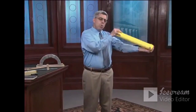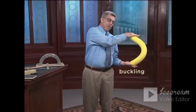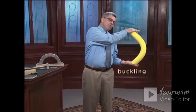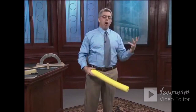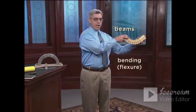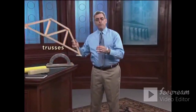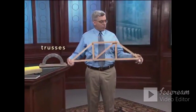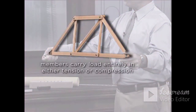And columns are also characterized by a unique failure mode called buckling, in which the element suddenly displaces laterally in an unstable failure mode that actually is the cause of a number of important structural failures that we'll be talking about later on in the course. Beams carry load by bending or by experiencing flexure. Trusses are structural frameworks that are composed entirely of interconnected triangles, as you can see here, and those members, it turns out, carry load entirely in either tension or compression, normally both.